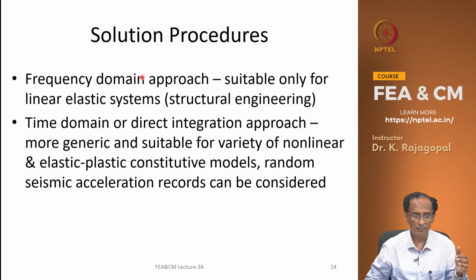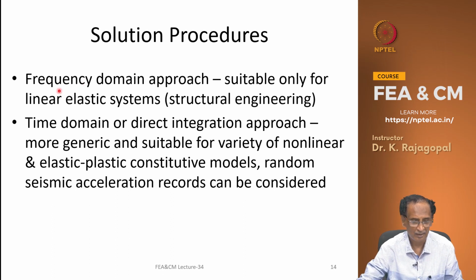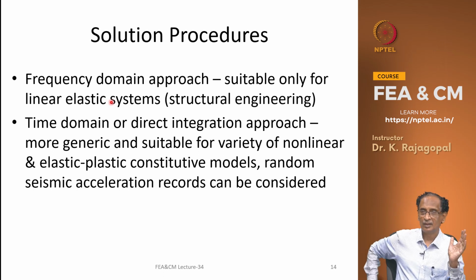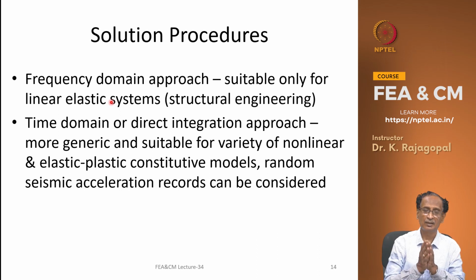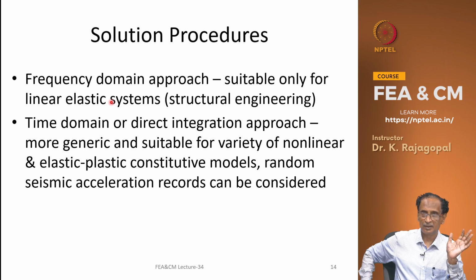approximate by different means. One method is the frequency domain approach. This is suitable for linear elastic systems, where we get the solution separately for different modes and then superimpose, and that is typical for structural engineering problems. And there we cannot incorporate the effect of any nonlinearity or the plastic deformation and so on.